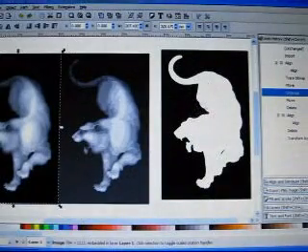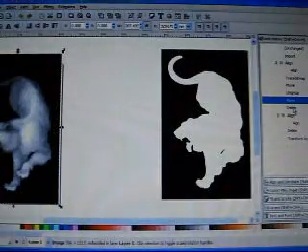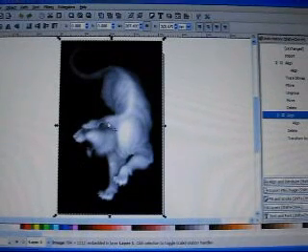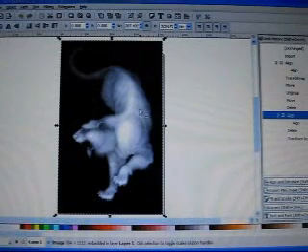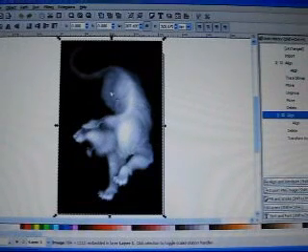Now this is the part that we do need. This is the information we want to extract here, is our outline. The extraneous information that we don't need, we just go ahead and delete that. And then we're going to go ahead and realign this left and bottom. Okay, and then at this point we want to save this, so we're going to save that as a PNG file at this point, and that'll be our raster image that we will give the program information for our depth map of the embossed tiger over here.